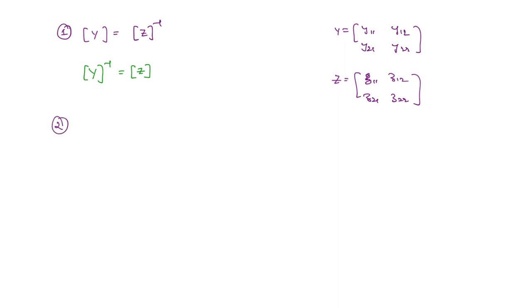Next, similarly the H and G parameters. Inverse hybrid parameters is nothing but the inverse of the H parameters. But the same is not true for the transmission parameters. This is not equal to the inverse of the transmission matrix. Okay, so this point is important.